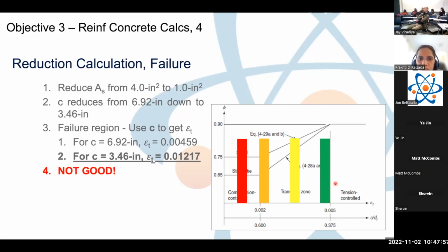We go from this transition almost in the tension control, that true running room, to the point that we are in the depth of our compression controlled zone. We are in a zone where, when failure occurs, whether it's at 220 kip feet or at 80 kip feet, it is a catastrophic failure, and you will look people in the eyes as they run down the bridge for safety, and they will fall instantaneously. This is a lot of weight, and we have to be serious about how we prescribe what allowable limits a structure is allowed to use.